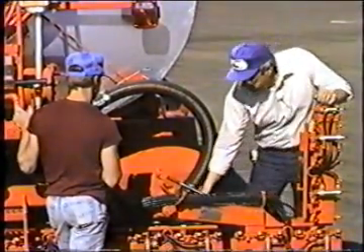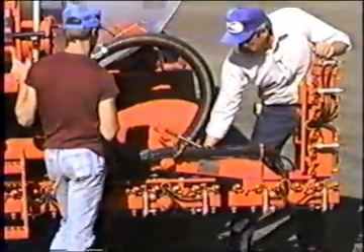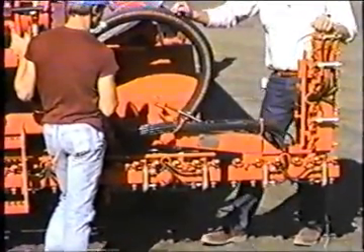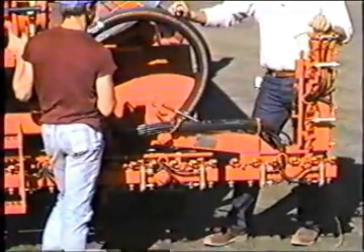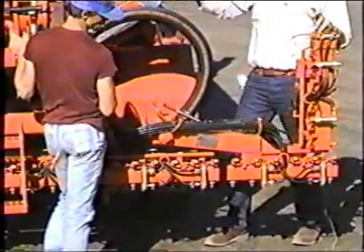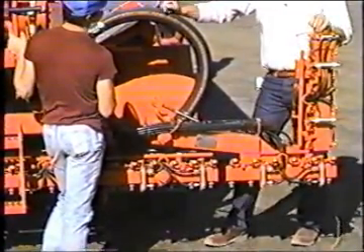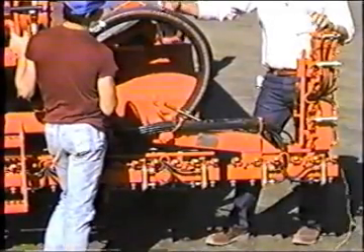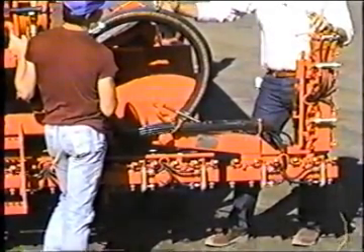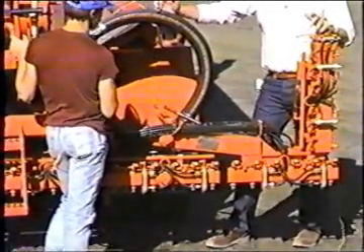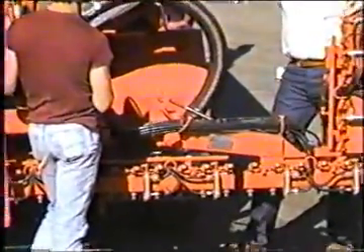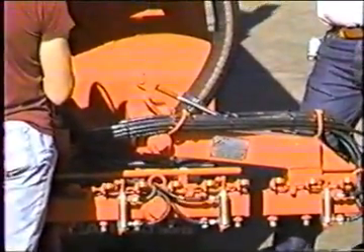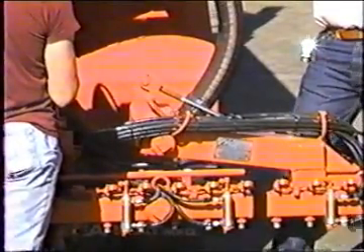Okay, we're into the bottom of the swing joint. That swing joint has got 2 passages all the way through it. Everything we're dealing with here has to be full circulating. We're dealing with asphalt materials that, at maybe 300 degrees, you can just barely cut with a knife. At 400 or 450 degrees they circulate freely.